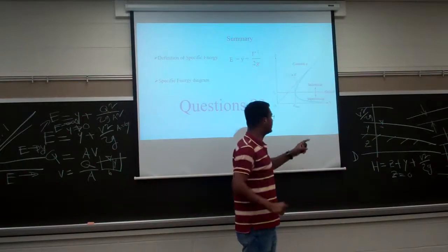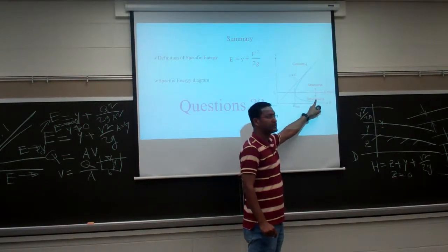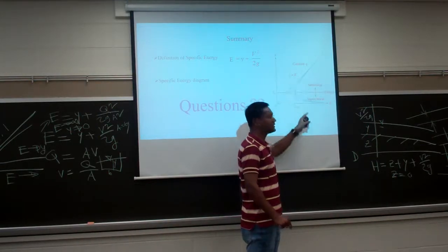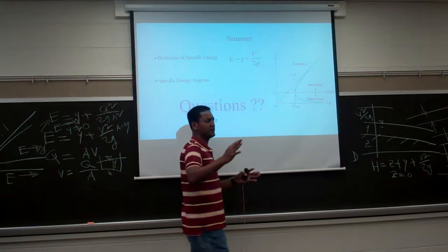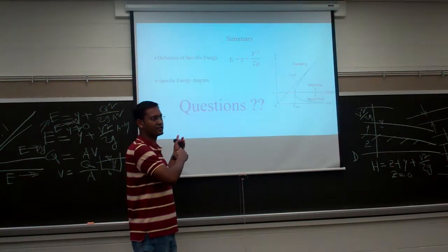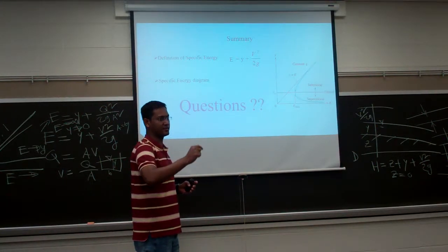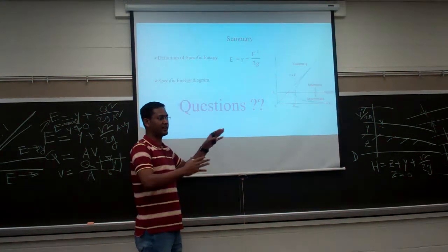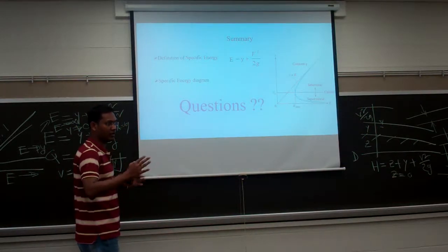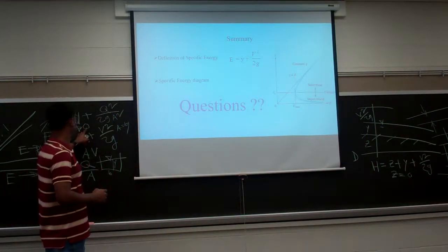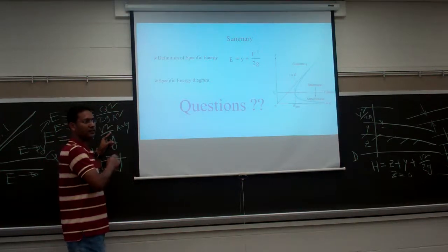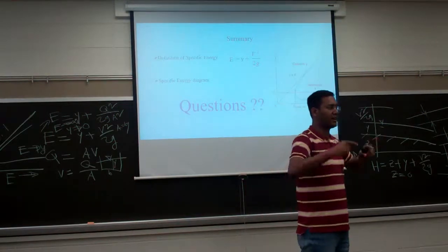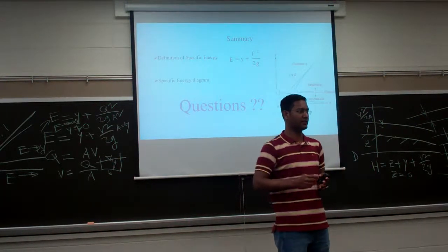So for each and every depth, we have a single point of specific energy. Right? For drawing this, you have to have a numerous number of points. Then we will get this continuous line. Since I am drawing the line as qualitative, not quantitative, I am assuming what will happen if the depth of water is 0 and what will happen when the depth of water will be infinity. I am assuming the lower limit and the upper limit.